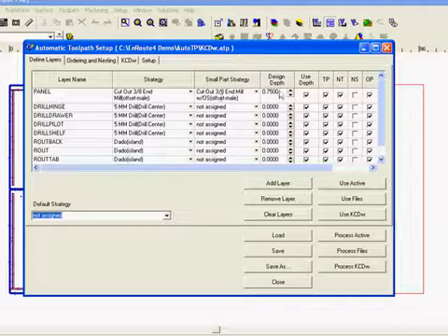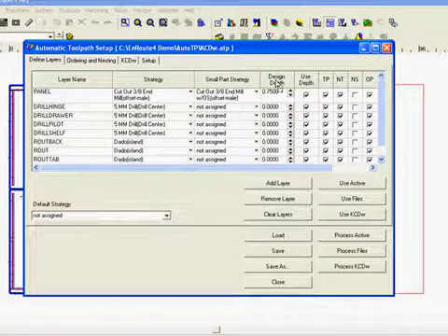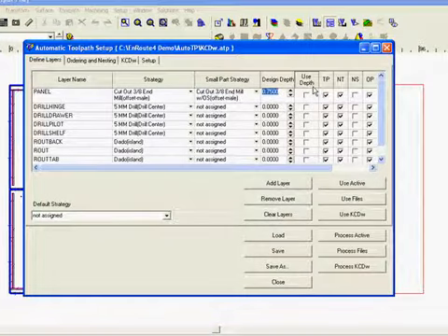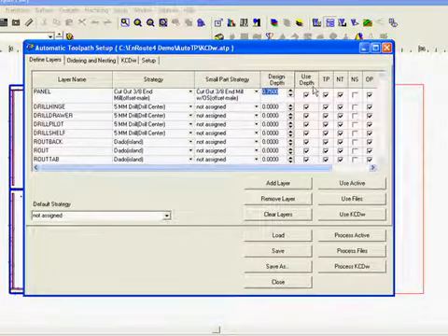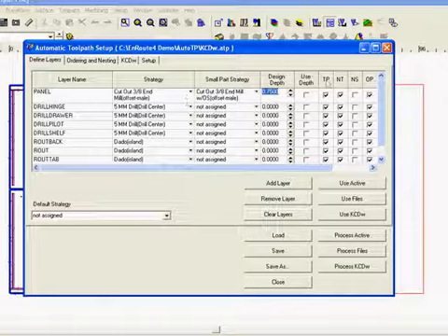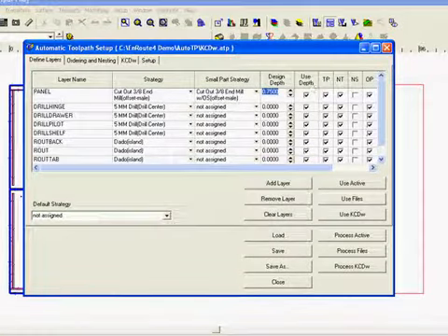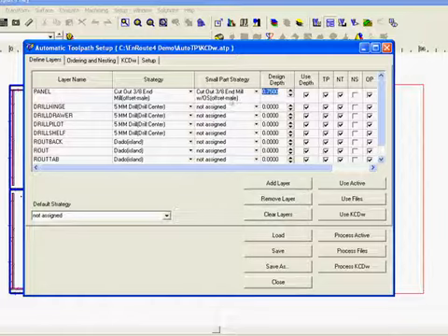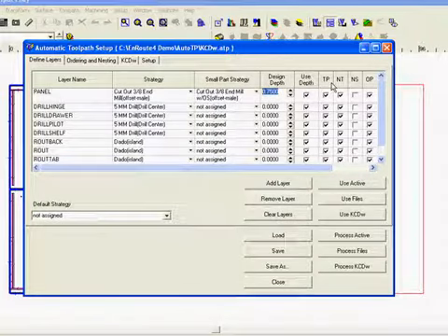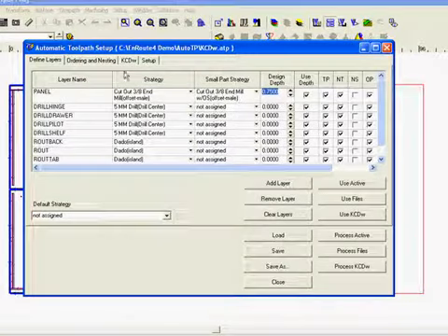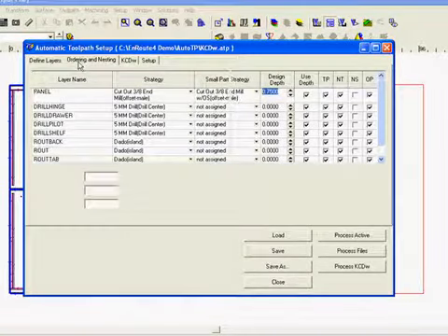All right, we have an ability to make your cut depth read off of the files, off of the geometries, and this is the use depth option. And by using depth, we're having the parametric program place the contour at a specific Z depth, and we're using that to determine the depth of the cut. We also have toolpath, nest together, and output selected here, and we'll explain all those in a different movie.